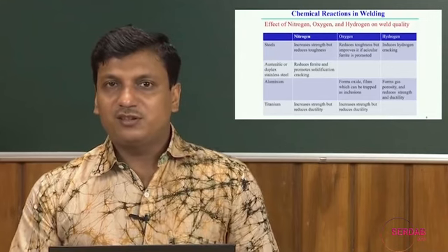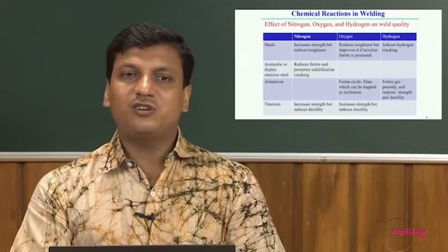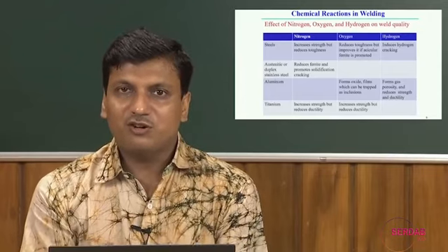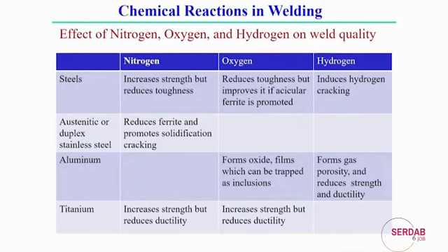So, probably it is a more serious problem for shielding as compared to normal steel components. In welding practice we have also seen that for titanium, extra sealing gas is sometimes required simply to protect the molten pool, because it has a very high affinity to react with oxygen and nitrogen.